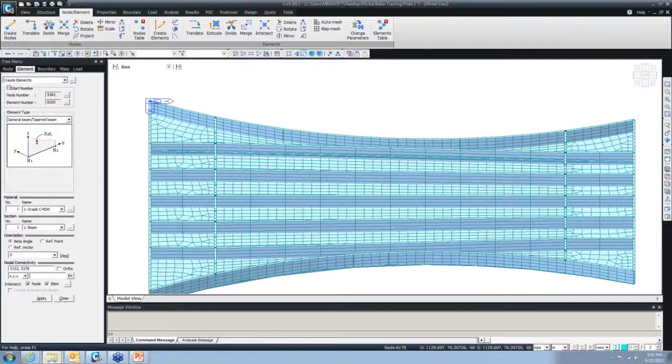You can pre-stress and post-tension all of those. You have the option to define the reinforcement or any post-tensioning or pre-stressing tendons in any geometry that you want. You can study the time-dependent analysis. So let me open Midas FEA and show you how easily and more cleanly you can work with this,